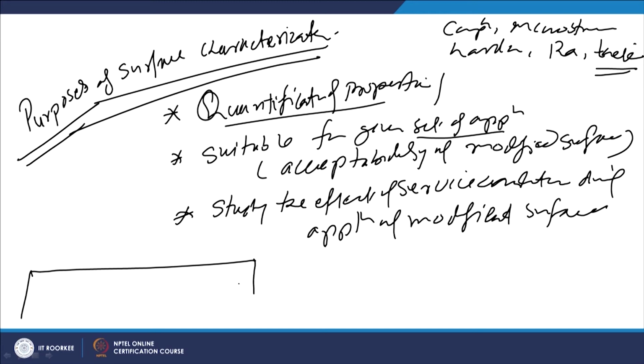What we can observe is, if the modified surface has been exposed to high temperature for a longer period, there can be loss of alloying elements, which will lead to modification of the chemical composition of the near surface layers. There can be enrichment of the alloying elements also. This can lead to embrittlement of the modified surfaces due to the enrichment; carburizing is one typical example of this.